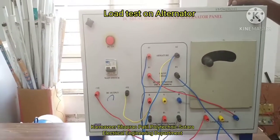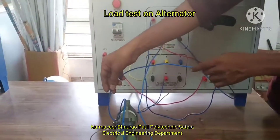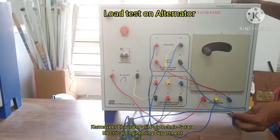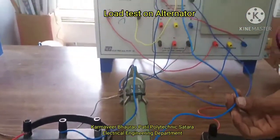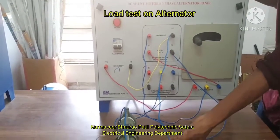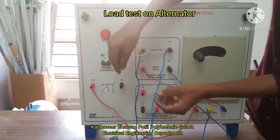Then where does F2 go? F2 goes to the rheostat. So it is connected to the fixed terminal of the rheostat, and the other terminal of the rheostat, that is the variable terminal, will be connected to A2, and this A2 will again go to the negative of the supply.